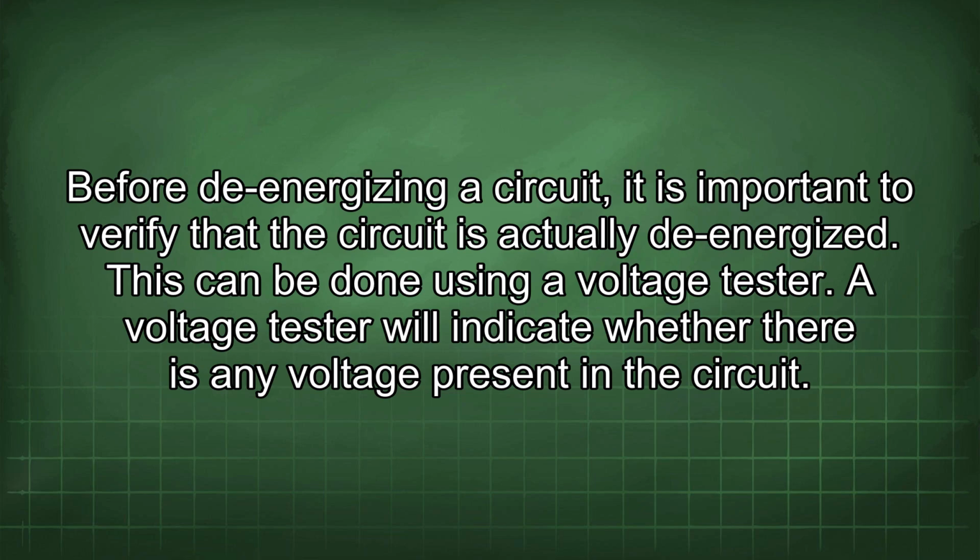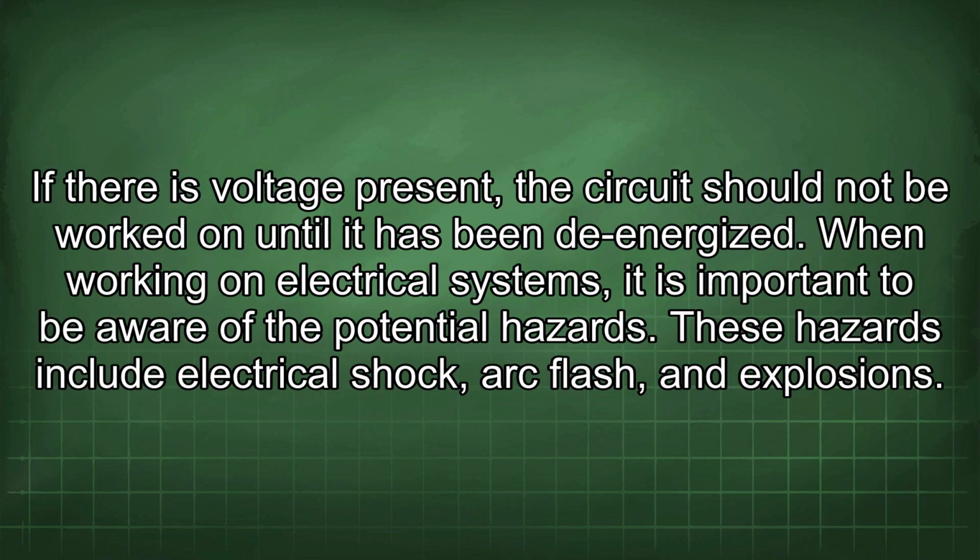This can be done using a voltage tester. A voltage tester will indicate whether there is any voltage present in the circuit. If there is voltage present, the circuit should not be worked on until it has been de-energized. When working on electrical systems, it is important to be aware of the potential hazards. These hazards include electrical shock, arc flash, and explosions.